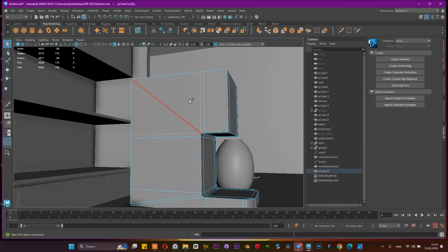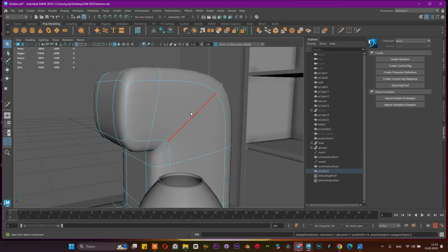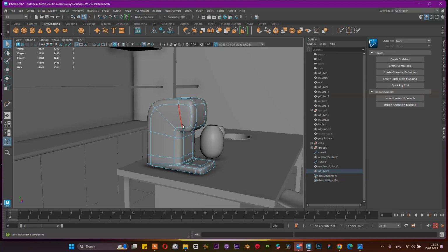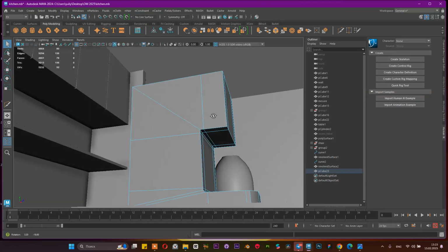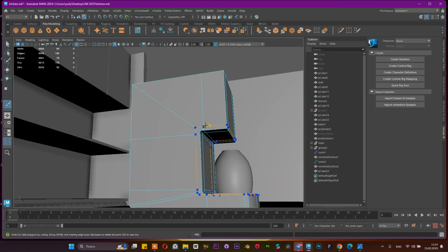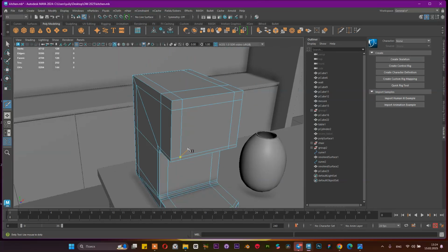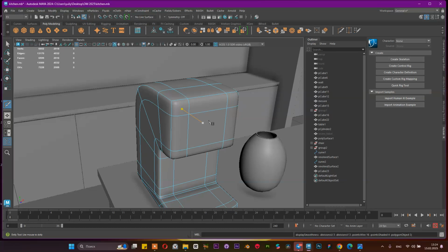And I'm going to delete these construction edges. And now if we subdivide, it's more accurate here, like a tube. And after that, we can add some multicuts around these corners, something like this. And in the end, this modeling process, it calls subsurface, or not hard surface modeling.